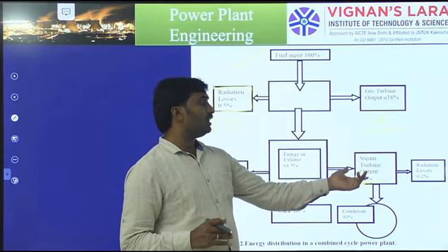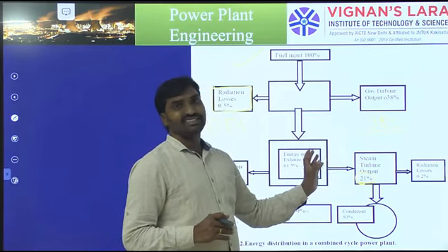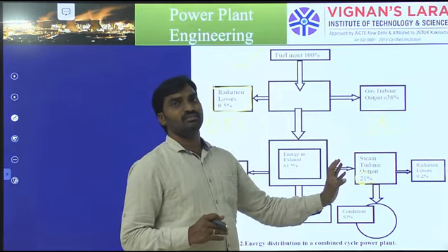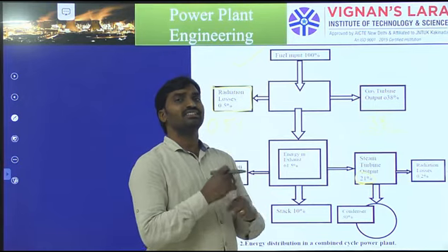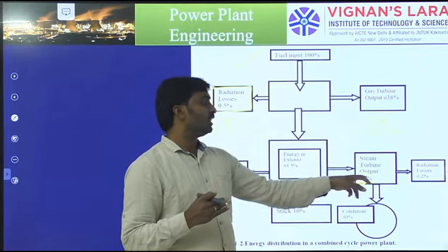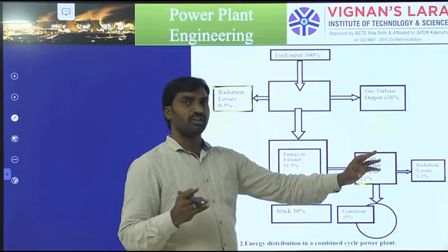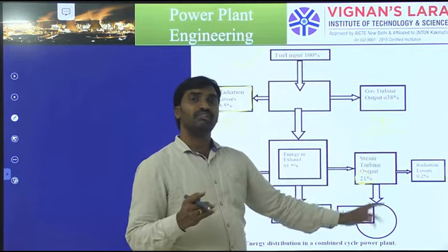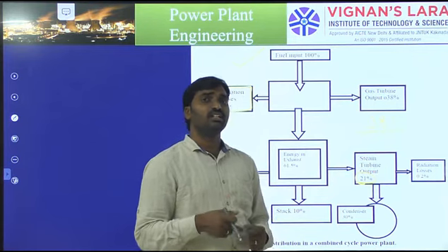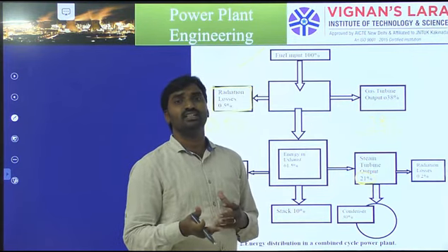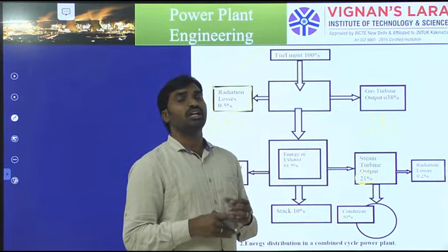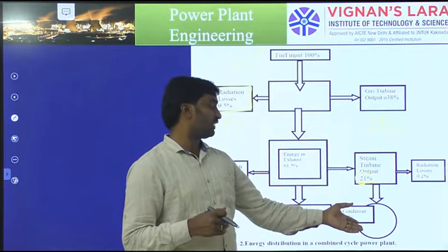Here in place of a boiler we are using the direct exhaust gases. We flow the exhaust gases over a boiler and generate the steam. That steam flows onto a turbine, where it expands, and then we need to convert it into liquid by using a condenser.